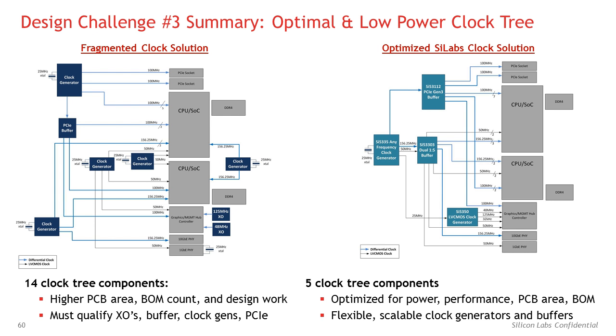As a quick summary, embedded processor designs typically comprise of complex clock trees, providing clocks for PCI Express, Ethernet, system, CPU, memory, and other I/O. As bandwidth and speeds increase, so does the need for higher performance clocks. Energy efficiency and low system-level power consumption are also becoming more and more important design factors.